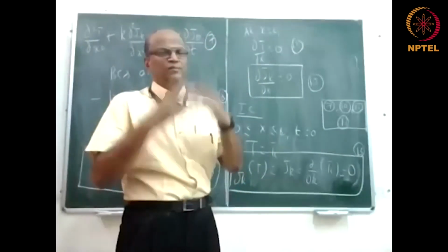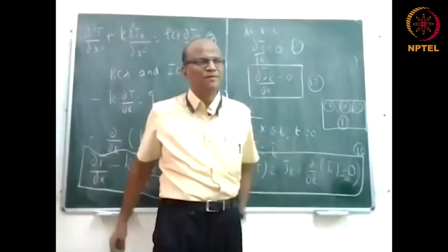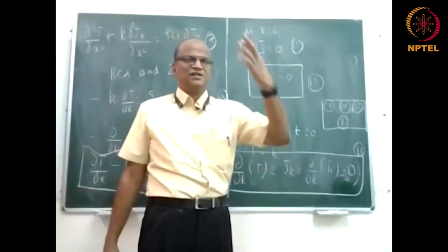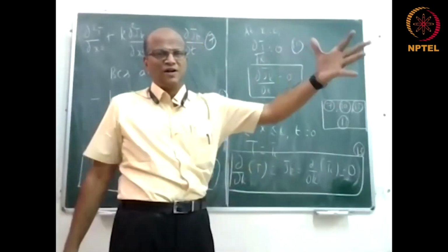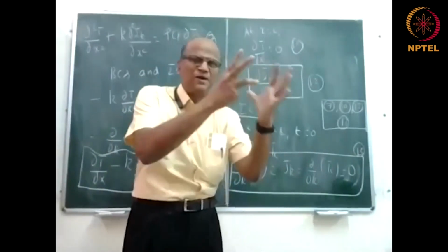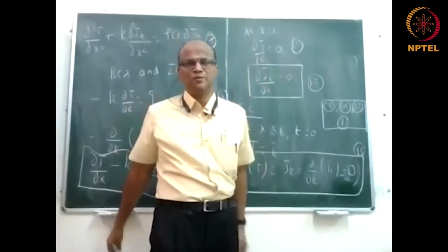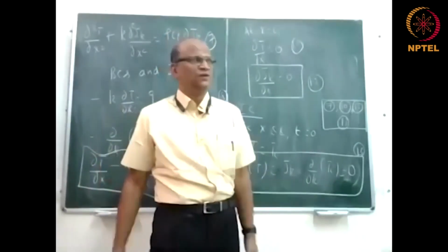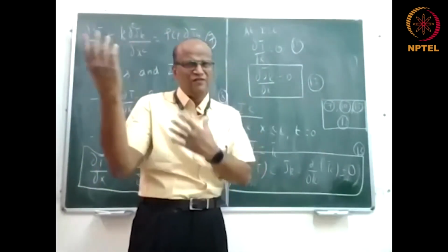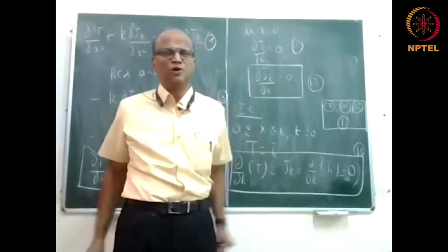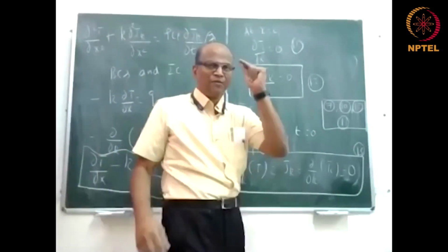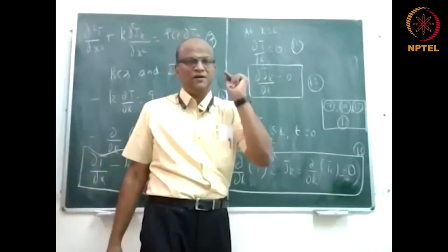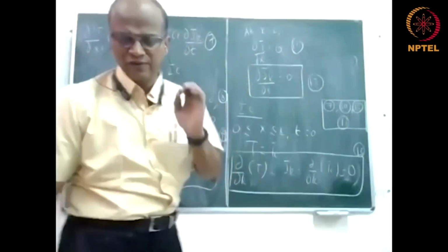Much in the same way, you can work out a Jacobian map, plot it in various colors, and say that the Jacobian is strong here. I want to look at this part very carefully to solve the inverse problem. There is something called computational frugality and experimental frugality: if some other person who is not smart uses 100 thermocouples, I'll just use 8 or 12. But by solving the Jacobian, I'll head straight to the answer. Is it okay? So this is the use of the Jacobian.